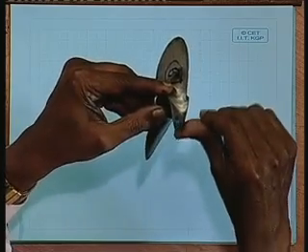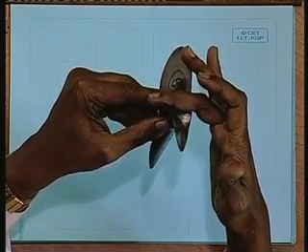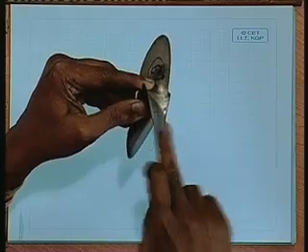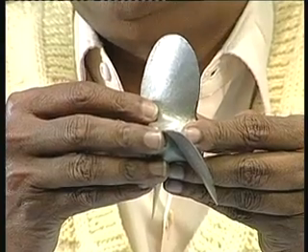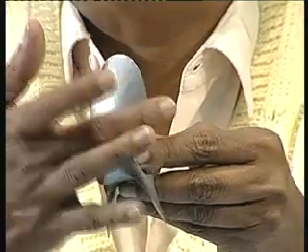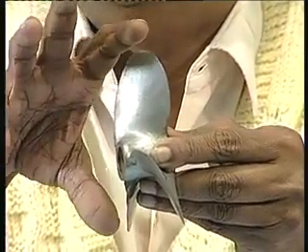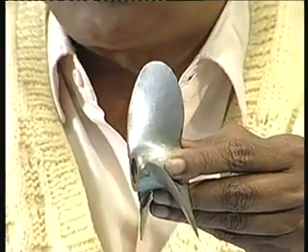So, that is called the leading edge of the propeller, and the other one is the trailing edge, right. This edge trails the propeller. Am I clear? The farthest point of the propeller blade is called the propeller tip, and the one that joins the propeller blade to the boss is called the root. So, I got the root, the tip, the leading edge, the trailing edge, the face and the back. This would more or less define all the main features of a propeller and number of blades, of course, along with RPM and torque it is supposed to observe.